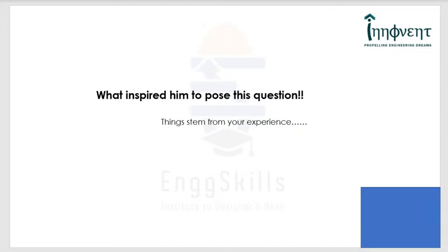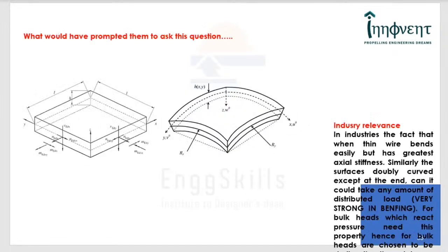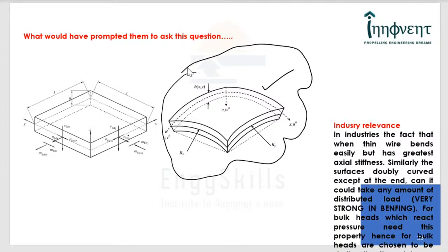So now, if you look at these two structures, that is, one is the plate, another is a doubly curved member, it is obvious that, if you have had a lesson on plates and shells, you would immediately recognize that the shells are far more structurally efficient. That means if you are looking at supporting a certain stress level, a very, very thin doubly curved shell can support what a very, very thick plate does. The idea can be incepted from a very, very small situation.